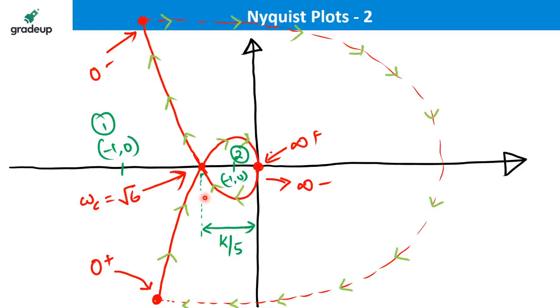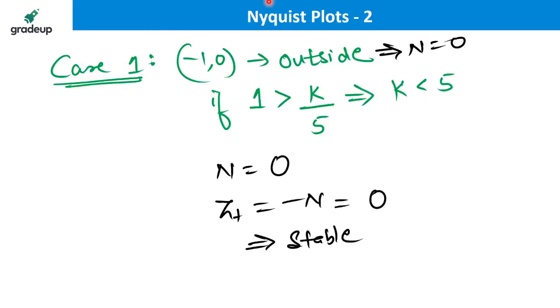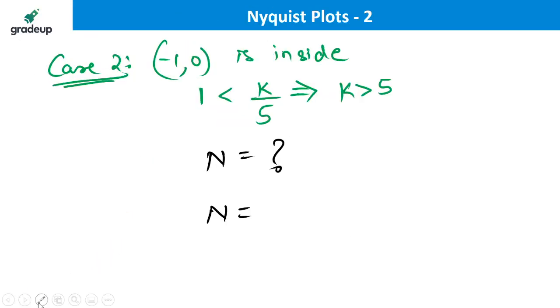Tick. Now look at the next one. Take from here. Outer loop. Just follow. The outer loop also completes one more circle. I come back to the same point, so it is also encircled by the outer loop, and again the direction of movement of the outer loop is clockwise. I will write down the results here. N is equal to two encirclements